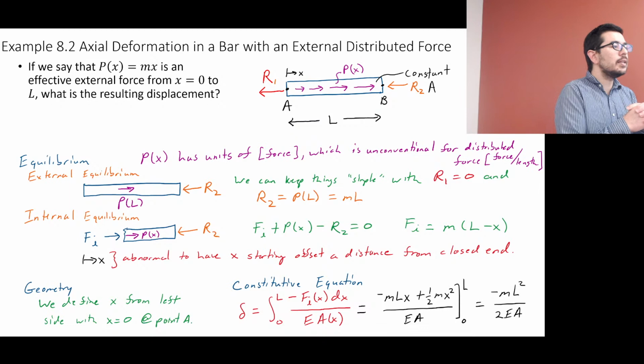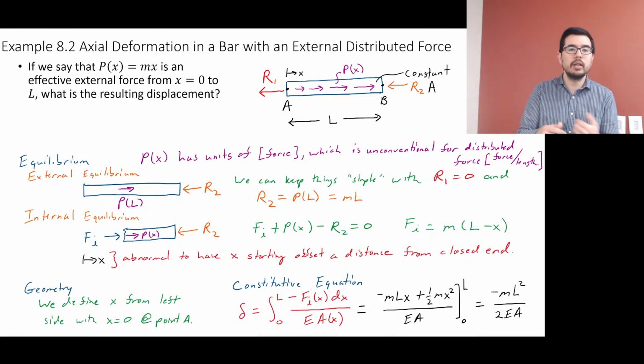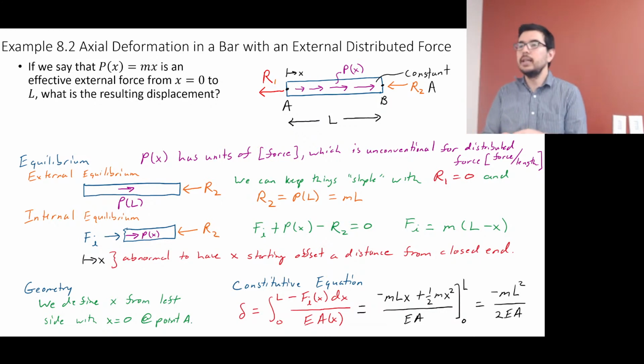So it's important that we figure out what the internal force is when we're doing these axial loading problems before we go ahead and apply the constitutive equation. Okay? And even though I got a right answer when I did it last time, that didn't mean that the methodology I was using was clear. Because if I had said that was an external force acting on the system, then I would have gotten the wrong result.